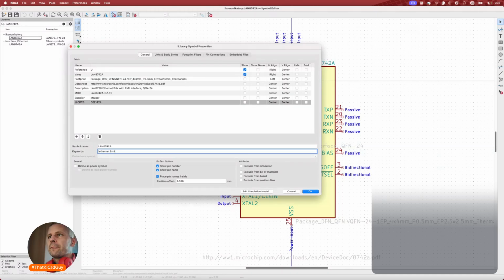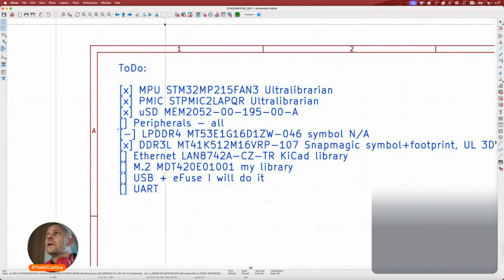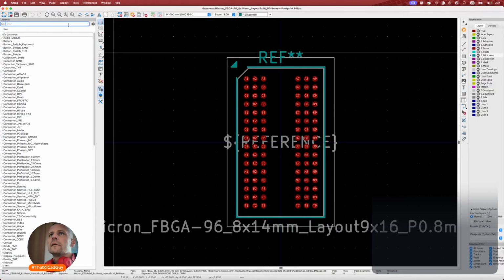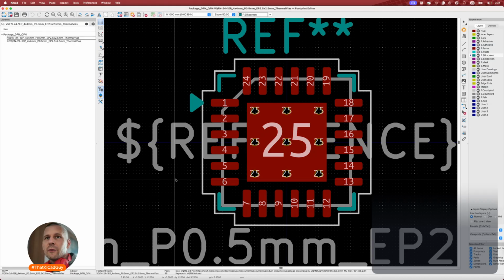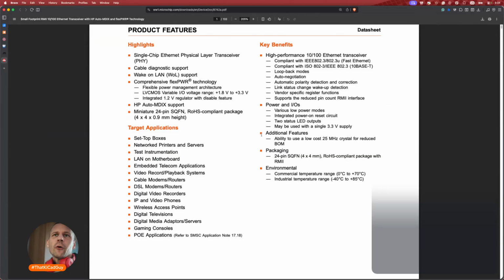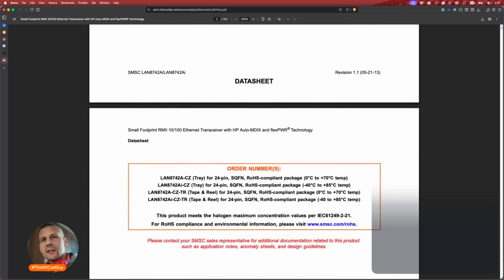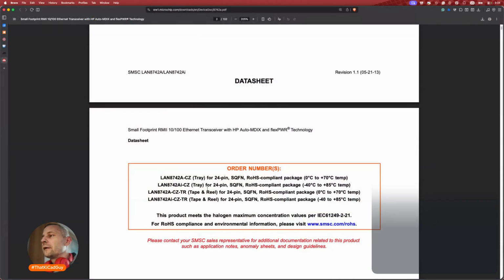Ethernet, okay, and I said we have to work on the footprint. I have it in the memory here. Here is the footprint used by the KiCad standard library, but it doesn't mean anything. I have to check the datasheet for the recommended footprint. The recommended footprint from the datasheet is what I take as a golden standard for each component, because anyone who creates these libraries, either at SnapEDA, Ultra Librarian, or the KiCad standard libraries, can be wrong.